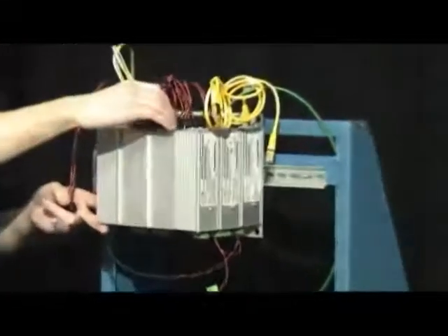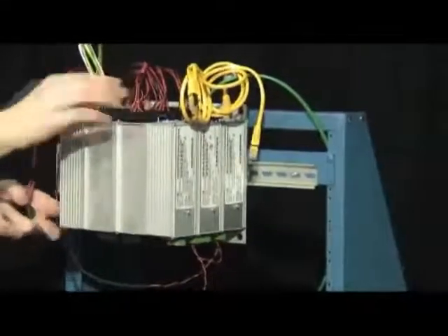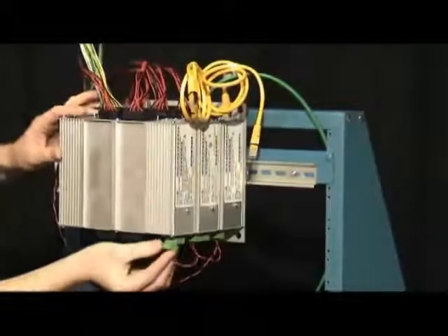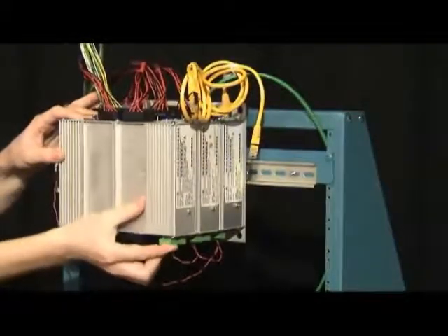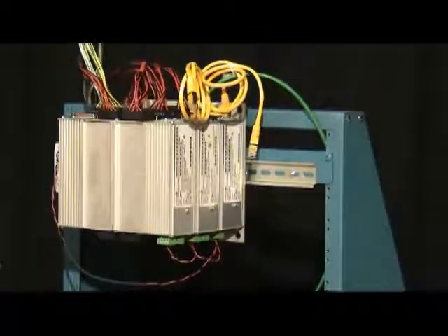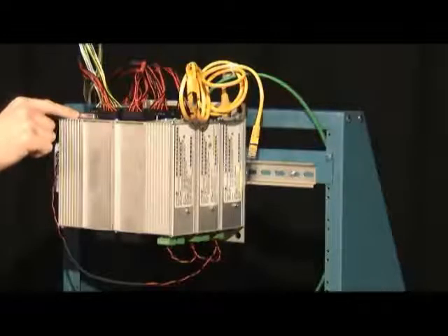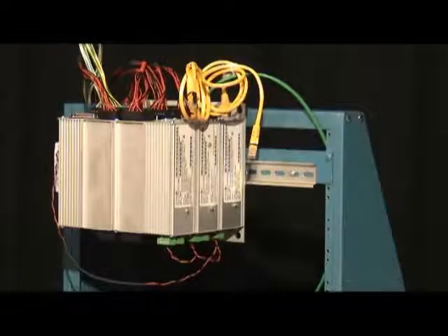First, you just plug your sensor signals into the pluggable terminal blocks here. Now your power signal also comes in through a pluggable terminal block on the bottom. Now with the voltage input and output units, you can also use the optional DB25 connector to connect to any of our line of 8B isolation amplifiers to provide up to 1500 volts of channel-to-channel isolation.